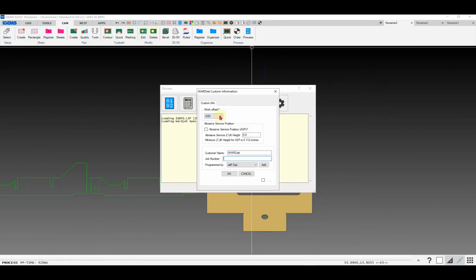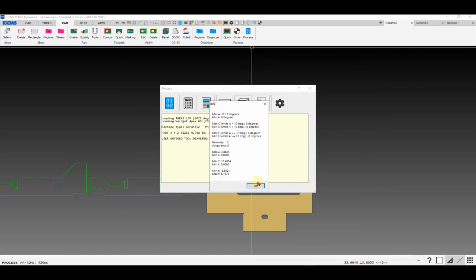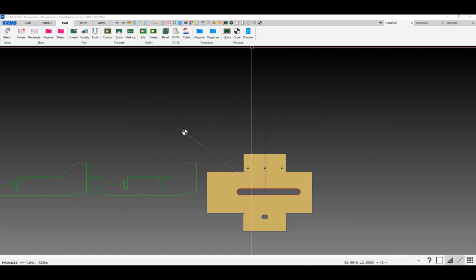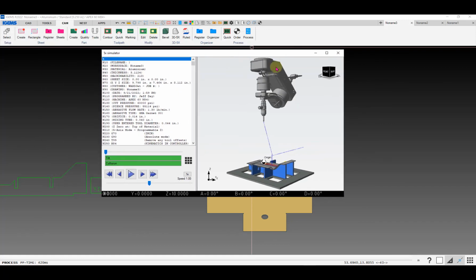And then this might be a nice application where, rather than doing G92, where all your coordinates are based off of wherever you start your program, we could choose G54 work offset position. All the coordinates are based off of the G54 saved position in the controller. Therefore, you can basically start the cutting head wherever on the table.